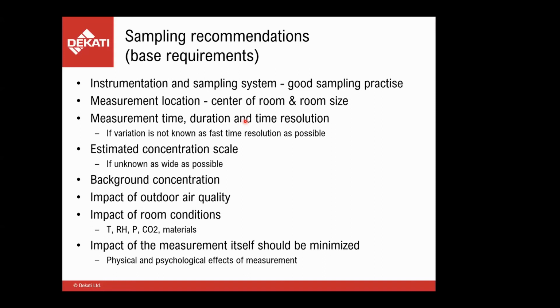So there are those sorts of limitations. There are requirements for the measurement time, duration, and time resolution. If you don't know the variation of concentration in a space, then you should select methods that have as fast a time resolution as possible so that you're able to catch those events.